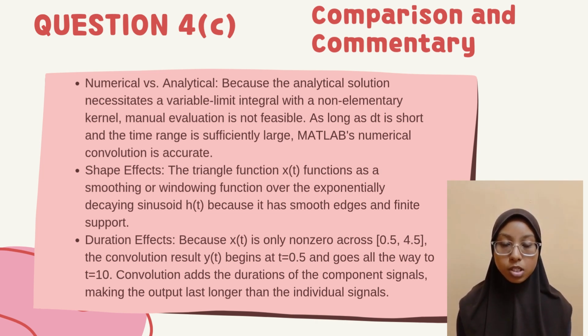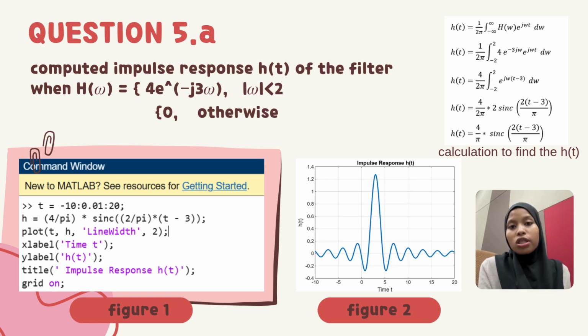and by hand is the best evaluation. So here is the equation h(t) which we have to find so that we can put it in the coding. h(t) equal to 1 over 2π integrate from negative infinity to infinity H(ω) times exponent of jωt dω.